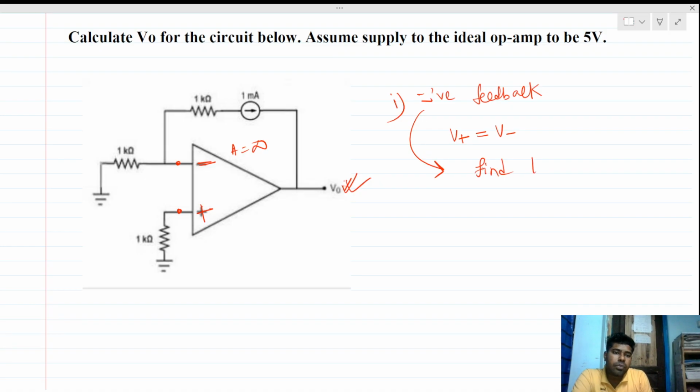We find the loop gain. For the loop gain, we cut a point on the loop, traverse the loop and get back to the node again, and see whether there is any 180-degree phase shift or not. This is the way to find the loop gain, and then we have to deactivate all the independent sources.